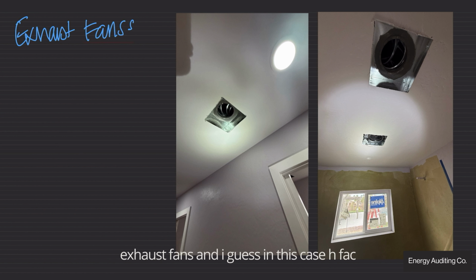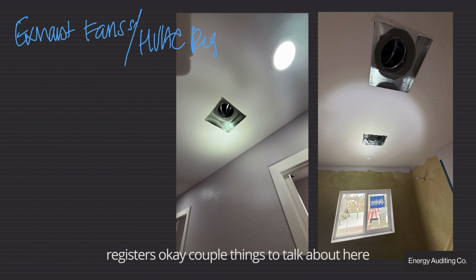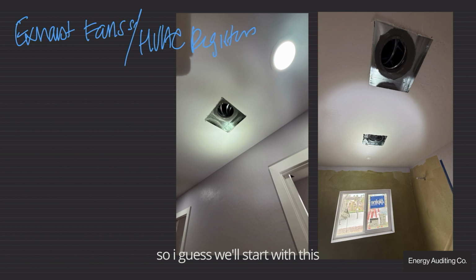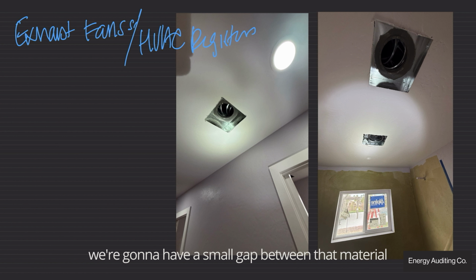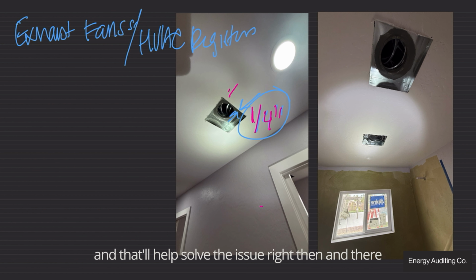Exhaust fans, and I guess in this case, HVAC registers. Okay. Couple things to talk about here. So I guess we'll start with these HVAC registers. We're going to have a small gap between the drywall and the can, and it's like a 1/4 of an inch, right? It's typically what we see. We typically have a 1/4 inch gap between those two materials, and hit that with some caulking, and that'll help solve the issue right then and there.